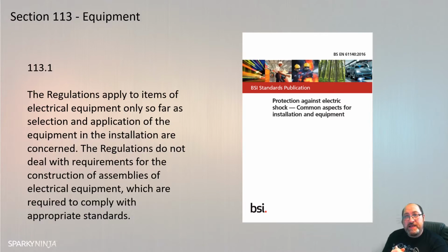We must make sure the equipment is designed and selected to suit use, normal service use, including, bear in mind you could be working with a client at quiet time. Ask where they're going to be going in 2 or 3 years. Are they planning on increasing production or increasing growth, for example? So is this electrical equipment going to be applying a lot more stress or under a lot more load in X months' time? So you need to try and get that picture when you select electrical equipment and verify that what you are selecting is suitable for service.